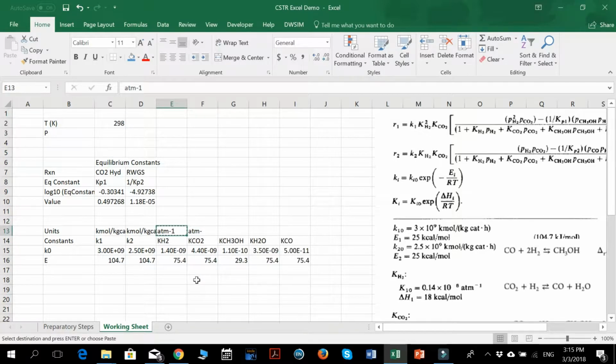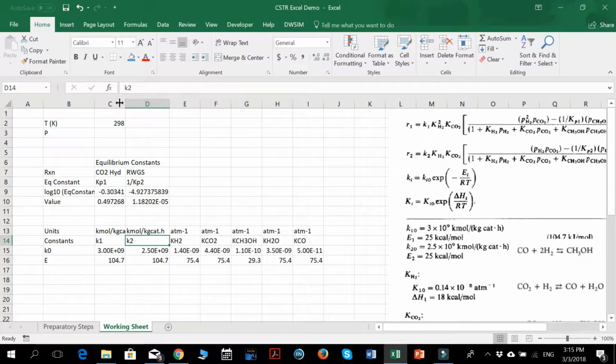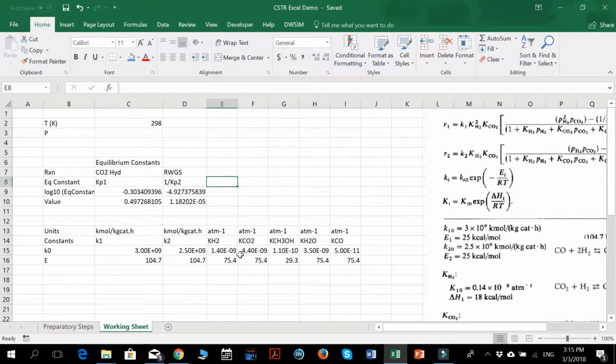To copy, I use Ctrl C, and if I want to paste over the next 4 cells, I move it to the right, and I hold Shift while pressing the arrow keys, and this will help to select the boxes as shown here. And I press Ctrl V to paste. I press Enter to cancel away the copying function. So yeah, this is what it should look like now.